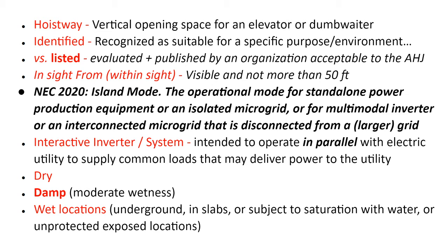Maybe they have a European listing that is equivalent to the US standard, but you might have to go to your local jurisdiction to say, look, we're using an ETL listed device. It's not UL listed. We just want to make sure that that's okay at the planning stage rather than the commissioning stage.